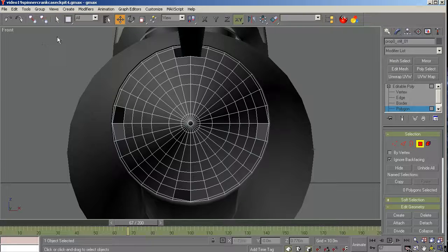Of course, it worked perfectly, as you would expect. Just as an example, I'm not going to take the time to do it here, but I've got 2, 4, 6, 7, so I grabbed all the polys all the way down, but excluding the center point here. Grabbed all these polys, deleted all these others because they didn't have the recess in it, and then used the array tool to just build me 3 more.